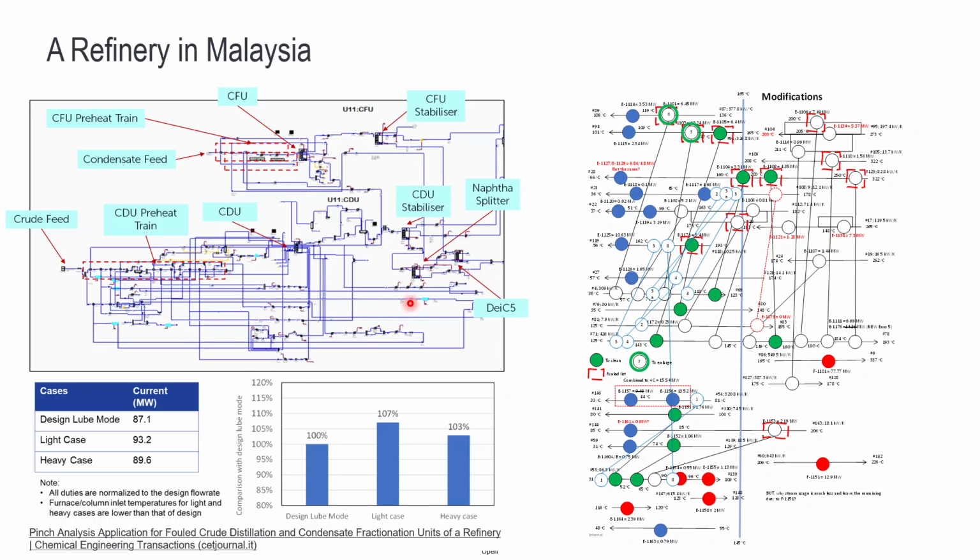In this case, we model that in a process simulation software, and then by doing so we can extract the data. I mean, like you guys are now modeling your final year design project, right? So you model that, and then from this model, from the mass and energy balance, we extract the flow rates, we extract the heat capacity, and then we extract the temperature in and out for each of the heat exchangers.